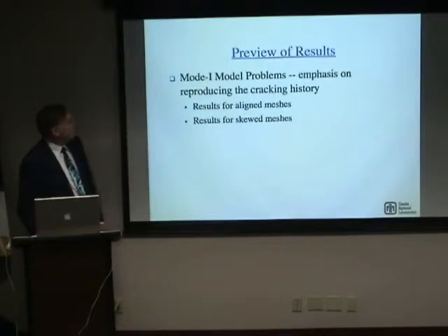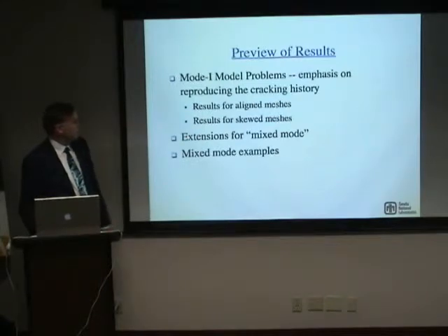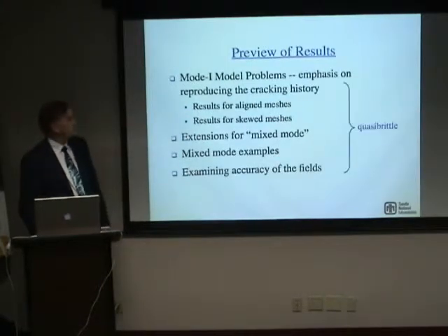So anyway, now I'm going to present results for using the general methodology that I've discussed briefly here, and the emphasis here is on reproducing the crack history in the first result. So we're going to look at the history of the crack tip and the cohesive crack tip as they go across the domain. Then we'll go to extensions for mixed mode, give mixed mode examples, and talk about the accuracy of the fields in the problem.